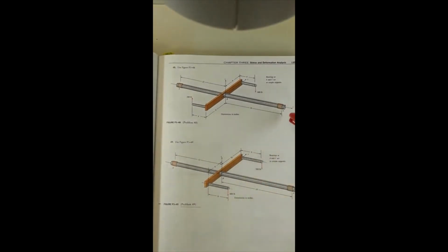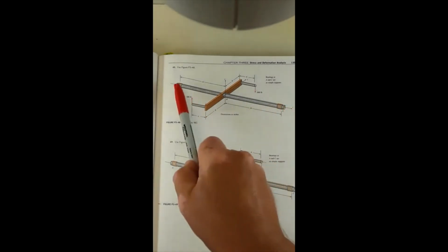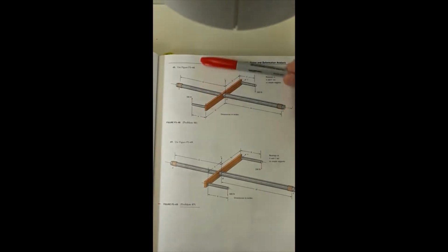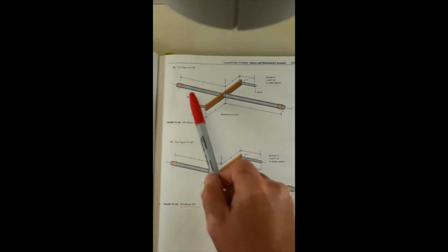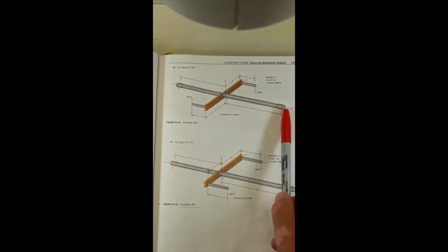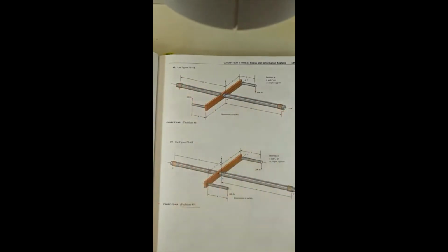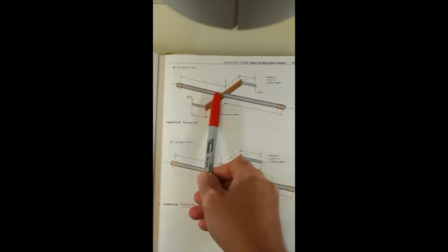It's assumed that the torque is resisted by the bearing at C. So for this portion ABC of the shaft, we need to draw a shearing force and bending moment diagram in the case of the vertical plane, that is YZ plane. And then I also need to draw a torque diagram of the shaft along the ABC line.